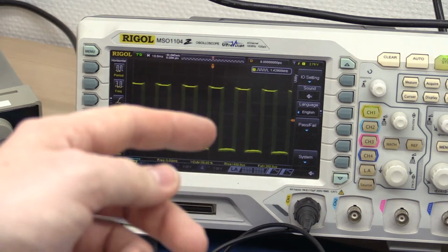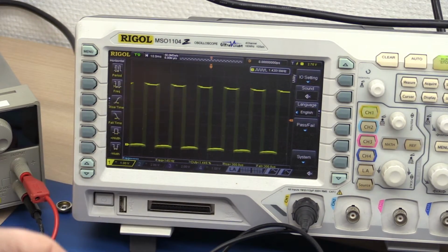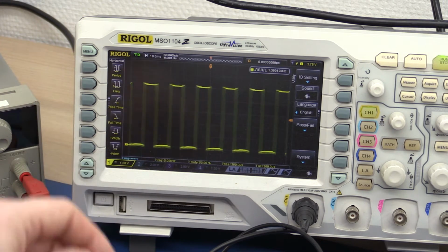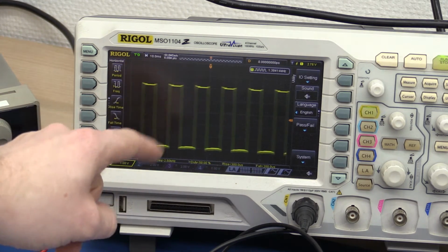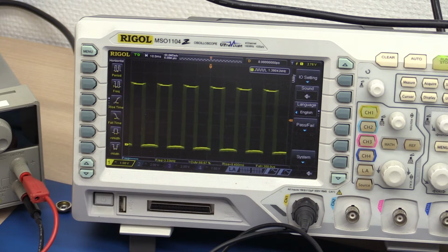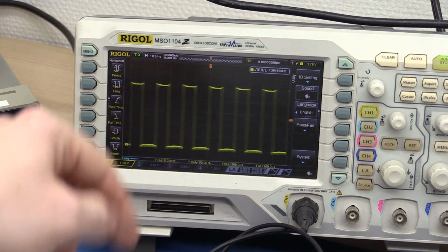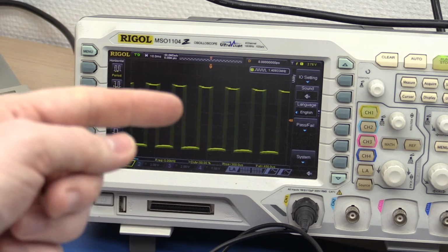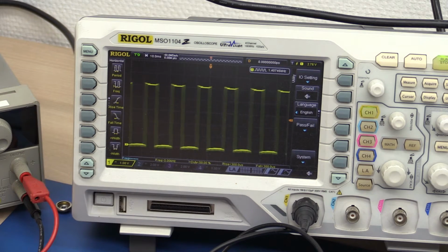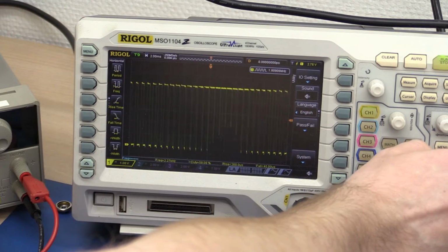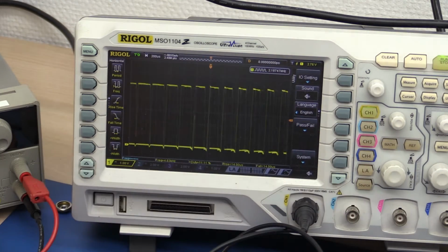So I hooked up the two circuits together in a comparator, and you can see we get a 100 Hertz square wave. I didn't hook up the input to the integrator, so it's basically just taking the 50 Hertz hum from the mains. If I touch this with my finger, you can see that it switches around, and we do get some kind of PWM signal going on.